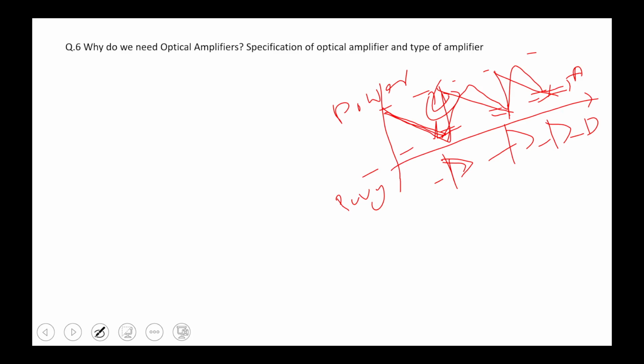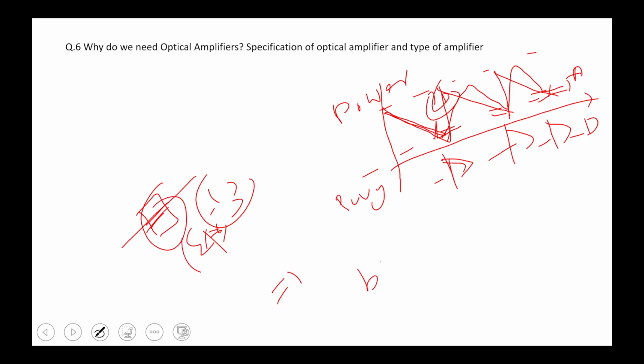So in the erbium doped fiber amplifier, we have the optical fiber and we dope this optical fiber with Er plus 3 ions. We have to do external doping in the fiber amplifier, and we use that to amplify the signal. In the semiconductor optical amplifier, we use an electrical signal. We have to do the biasing, and this will amplify the signal. External electrical biasing is used.